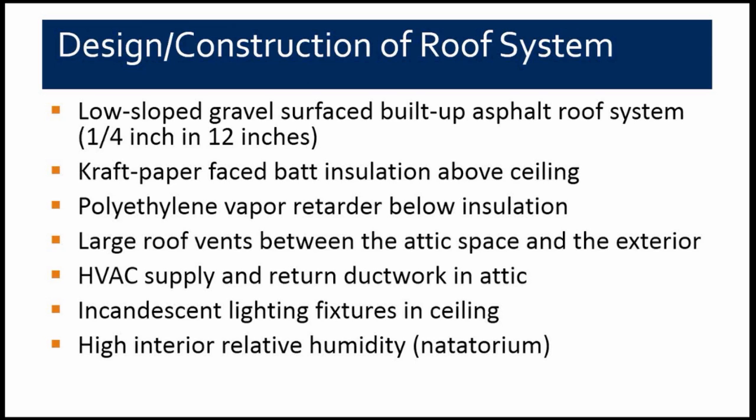They also had put large roof vents on the roof. It seems that the architect in this case felt that he needed to ventilate the space above the roof. And in the case of a sloped roof, like we talked about, this is exactly what you want. In the case of a flat roof, it's not what you want, and we'll talk about that in a second.